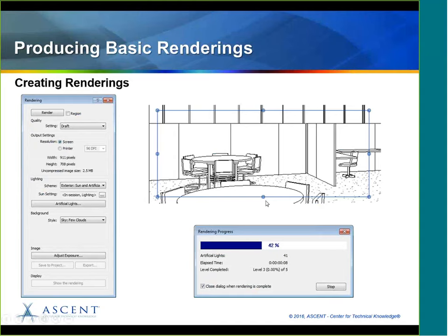This is the area of a larger view that's going to be rendered, and in this particular case, it's what comes out automatically when you choose this region button here. It automatically puts a box in, so don't try to draw one, I always try to draw one, and it doesn't work. So watch out, find the box, and then you can use the little controls here and change it around to show the view that you want to do.